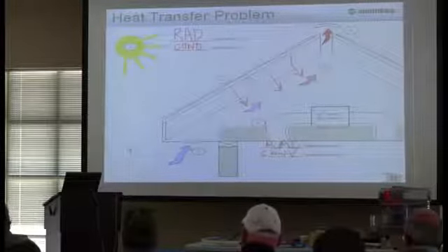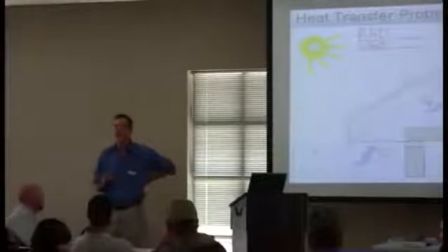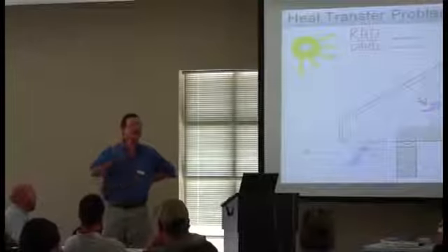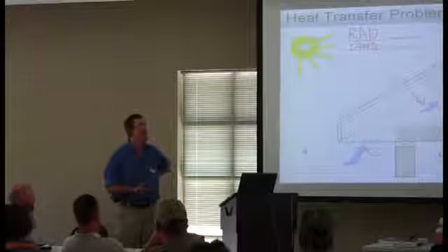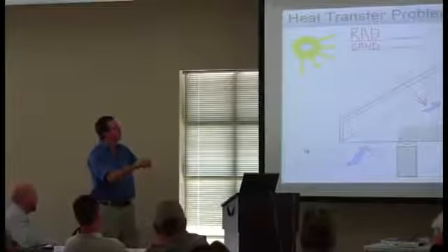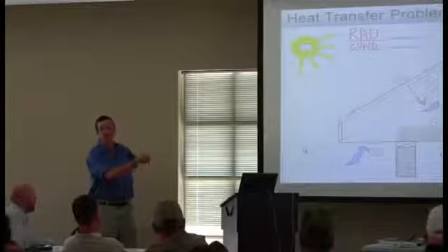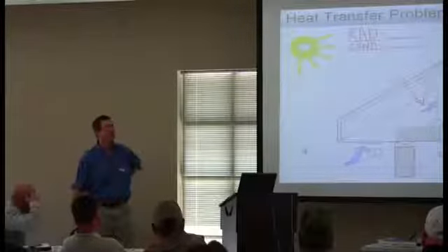We're really just treating a symptom, not the cause. Does that work for you? Does that make sense? We're only treating the fact that the air got hot, not why did it get hot in the attic in the first place. So really, the best thing we could do would probably be something shiny up here or less absorptive up on the roof. Any ideas? What's another roofing material?